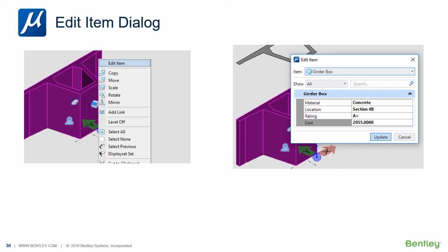So James, item types replacing tags in ProjectWise, we're looking at update 9, which would be March of next year. However, tags still work. So you can use tags in MicroStation today. You can use tags in ProjectWise. So there's no issue that you run across. It's all still fine. But ultimately, we will be looking at update 9 to start the switch from tags to item types in ProjectWise.